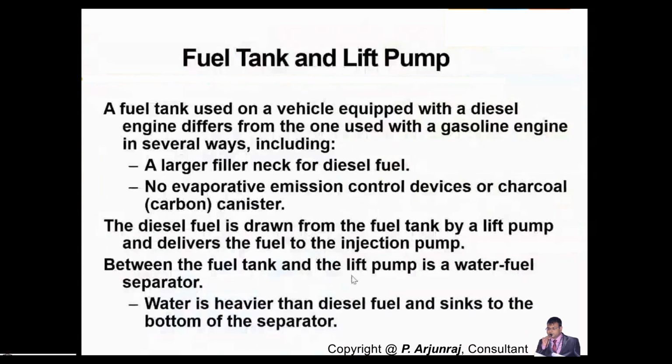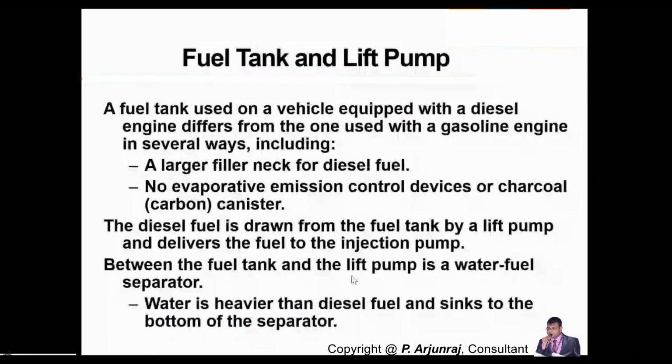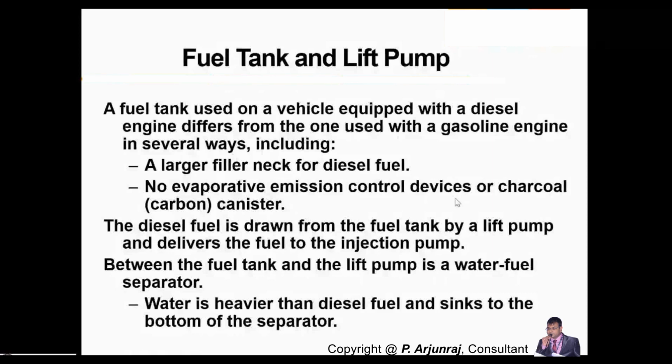With respect to the different components that we have for a fuel injection system, you have the fuel tank and the fuel pump. A fuel tank is basically different from that of a gasoline engine. The diesel fuel tank is different because in the case of a diesel system, you have a filler neck, and you do not have the evaporative emission control device or charcoal carbon canister device in the case of a diesel engine, whereas you have it for a gasoline engine.